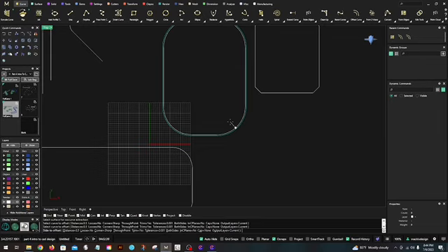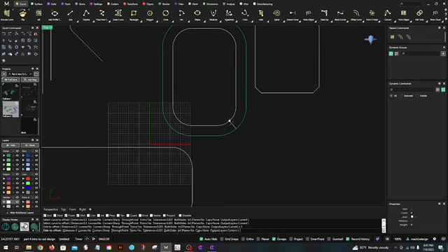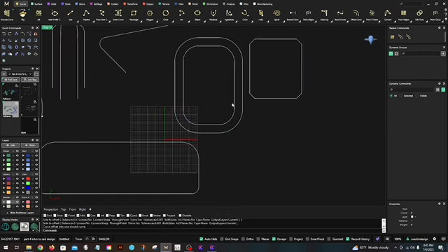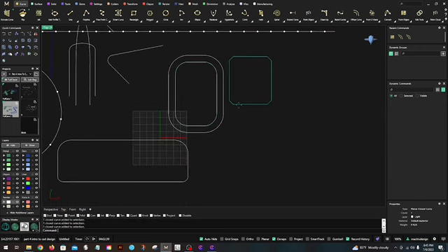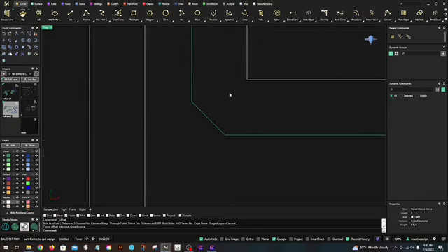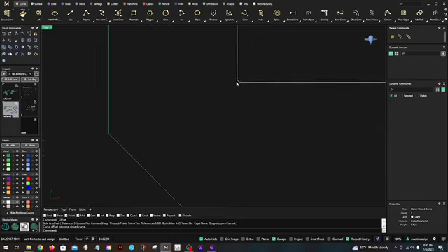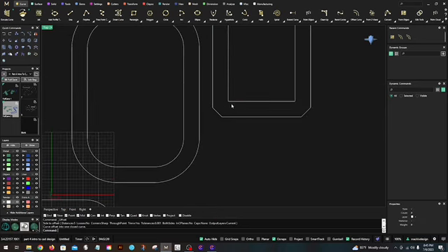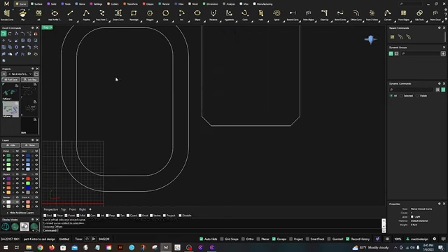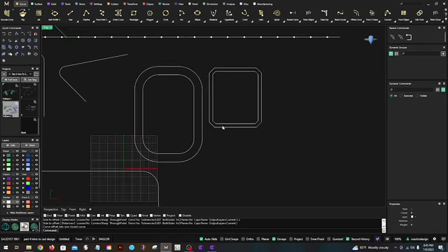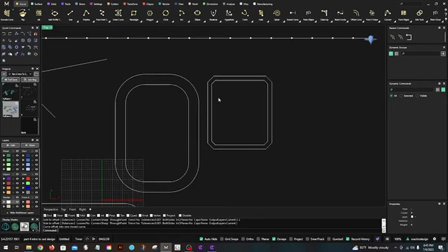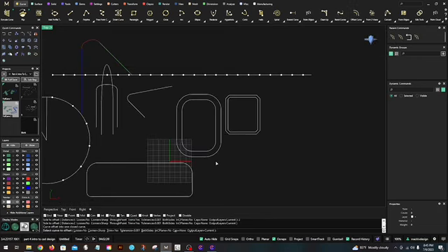I'm going to go ahead and punch in 5 millimeters and enter, or excuse me, left click. So here was my original, and here's the offset. Go ahead and do this one. Now you'll notice when you have clipped corners, this is actually clipped, but it's very hard to see. So it doesn't always work out maybe the best way. So if I offset this with just 2 millimeters, it would show a little bit more. But there is ways to take care of that if you want to adjust that. All right, let's do offset curve through point. Not sure.